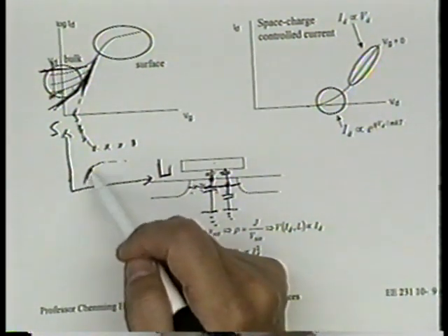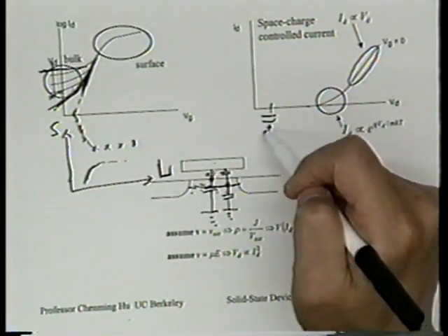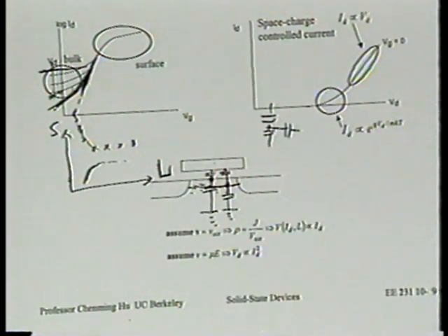Now, the good thing is that I wanted you to think the short channel effect is all one short channel effect. Whether it has to do with swing, whether it has to do with VT, whether with something else, they're very, very closely related. Why are they so closely related? They all have to do with this capacitance coupling, all have to do with the solution of the Poisson equation, all have to do with that barrier height. It's for this reason they're all one problem. Cannot separate them. The impact of the body, the impact of the gate, the impact of the back gate, they all relate into one. That's why they all happen at the same time. And so subthreshold swing is often used as another monitor for the short channel effect.